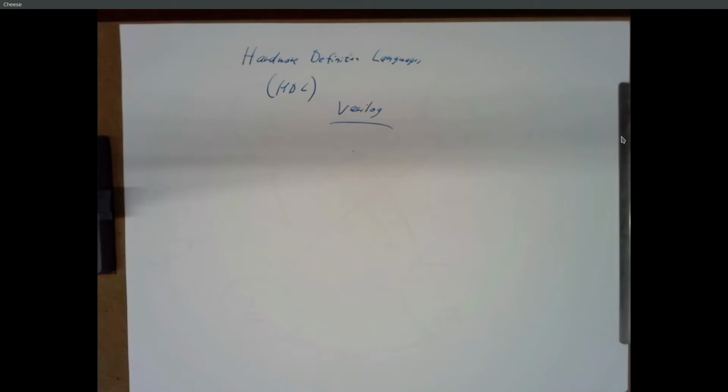So the most important thing to keep in mind when writing Verilog: you are not writing a program. It's going to look like a program. If you've done programming, that's going to hurt you because you're going to think that you're writing a program, but you're not. We are not writing an algorithm which says do this, do that, check if this is true, and now either go and do these things or do those things. That's not what's going on in Verilog.